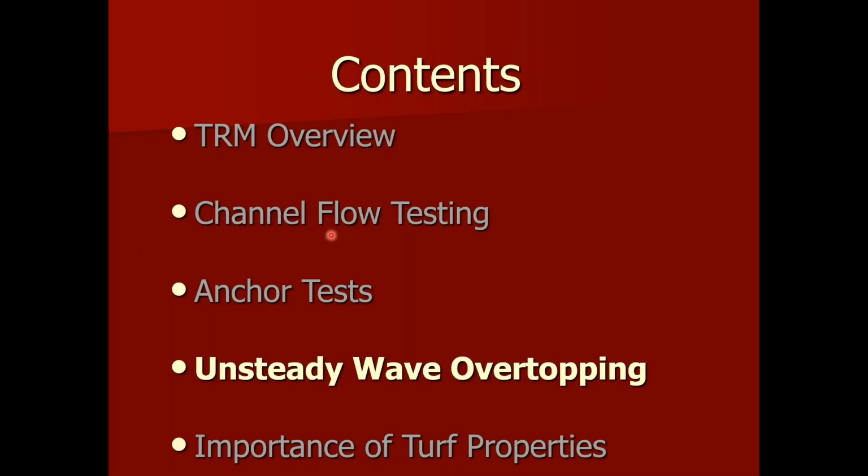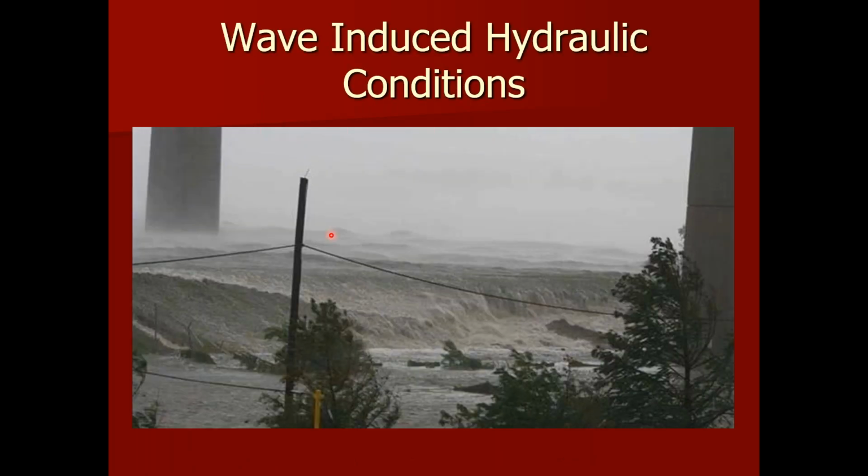I want to talk some now about the unsteady testing. It's the same idea. It's a hydraulic load, but it's a function of time. Unsteady wave overtopping, of course, a wave comes over the top of an embankment, then it's still, then a wave, then it's still. So it's that dynamic loading. There's an impact, there's a centripetal acceleration because of change in geometry and change in volume of each individual wave,